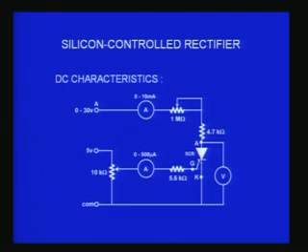and this is the SCR, and the cathode is connected. There is a voltmeter here between the anode and the cathode of the SCR to measure the voltage across the SCR. And if you look at the gate side, I have connected a 5.6 kilo ohm resistor in series, and a current meter 0 to 500 microamperes, and 0 to 5 volts I have put into a potential divider with a 10k resistor, so that I can change this voltage and find out at what current the SCR triggers on, the SCR starts conducting.